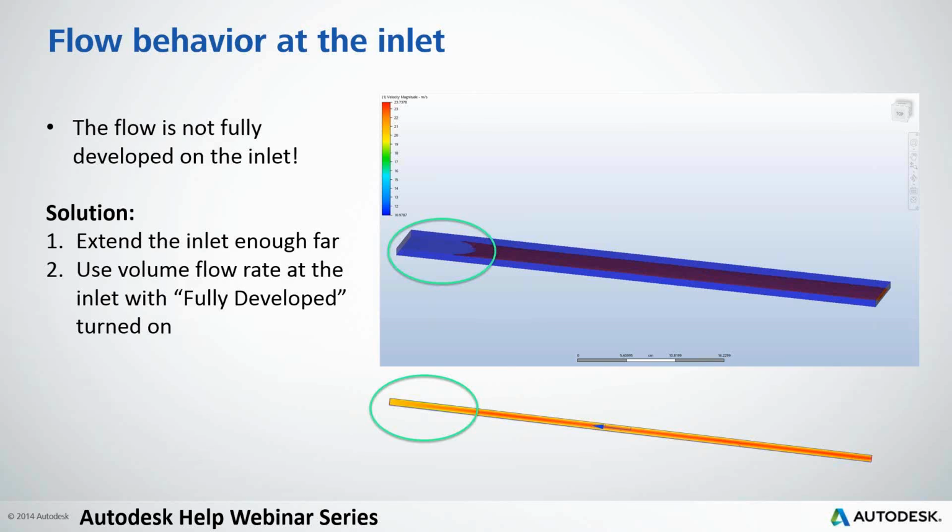Right. Basically, that's because you've got a uniform velocity, even when you're using a flow rate. Really what the software does is it calculates it down: we know what the surface area is and apply the velocity there, because your velocity times your surface area is the flow rate. But when you've got that velocity being pushed in near the corners, you're already going to be in the enhancement layer, so it's going to cause a heavy shearing right at the inlet. So you'll see a pretty heavy pressure drop, and that's kind of what you can see from that picture that Amal shows. Yeah, exactly.